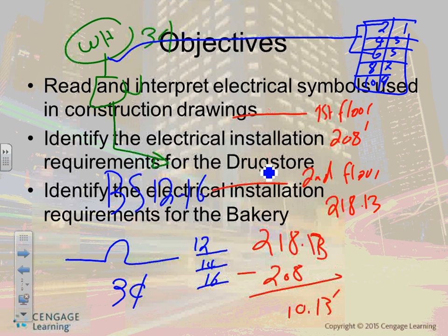Yes, sir. For the real estate panel, if this says 100 amps, there's no lugs, what does that mean? Real estate office. Yeah, because the owner is 200 lugs, and the real estate is just 100. 100 amp, it must be a circuit. Are you looking at the panel? Yeah, the panel. The owner, 200. The real estate office says 100. Yeah, it doesn't say lugs or anything else. It's a mistake. So let's look at the riser. No, it's main lugs. It should be lugs. That's a mistake. Should be lugs.